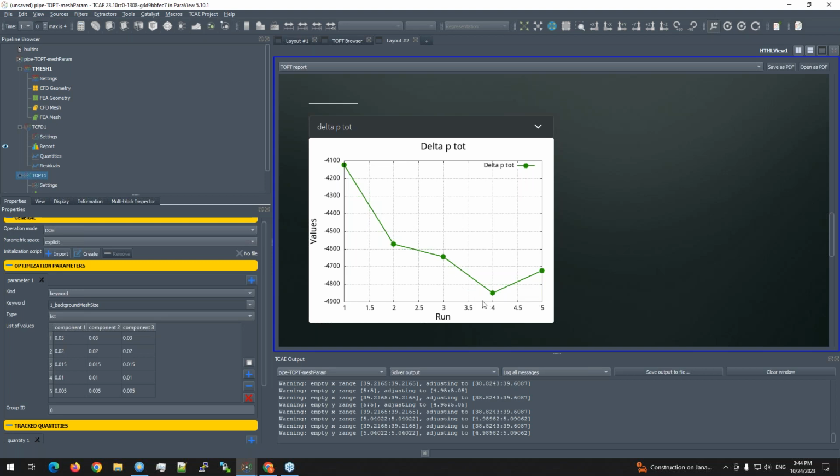And roughly speaking, about the setup of the meshes, we are pretty close to the constant value, we can call it. Or we can say that with further refinement we are not achieving better accuracy, the integral result doesn't change so much, so we can roughly say, okay, this refinement is enough for my goal accuracy, depending on the goal.